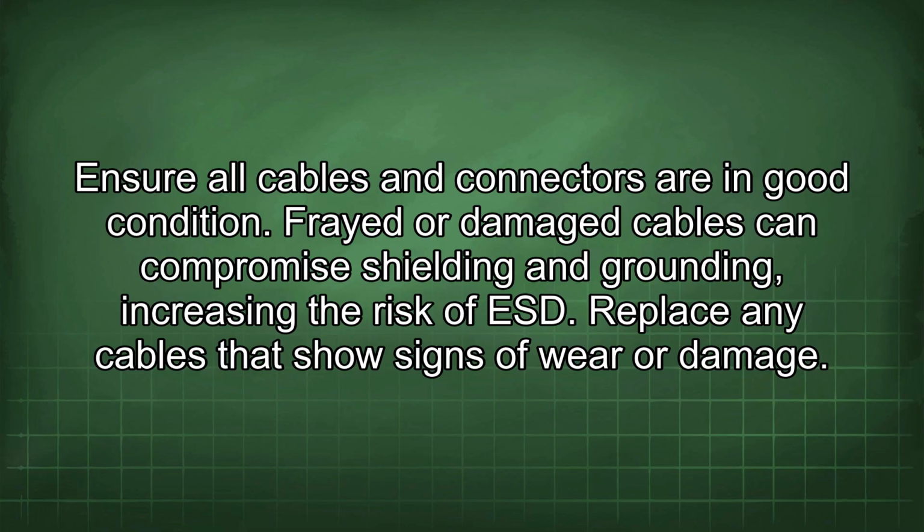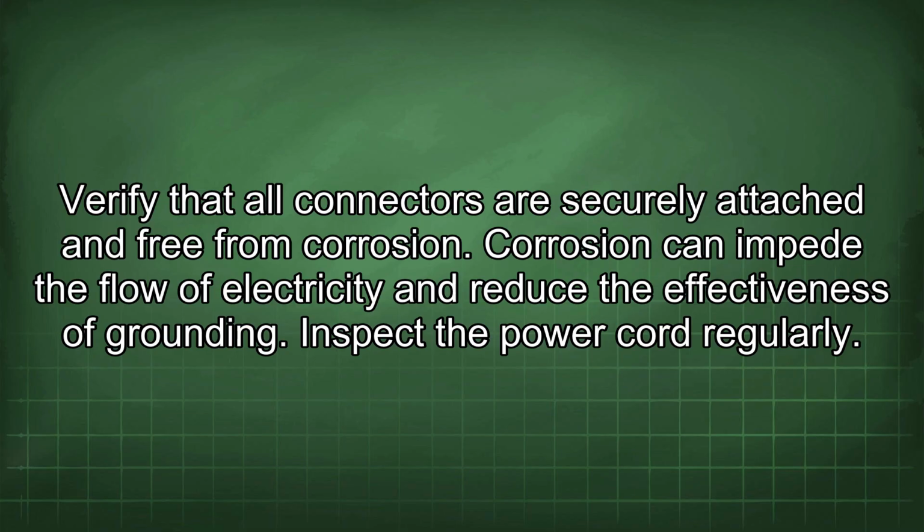Frayed or damaged cables can compromise shielding and grounding, increasing the risk of ESD. Replace any cables that show signs of wear or damage. Verify that all connectors are securely attached and free from corrosion. Corrosion can impede the flow of electricity and reduce the effectiveness of grounding.